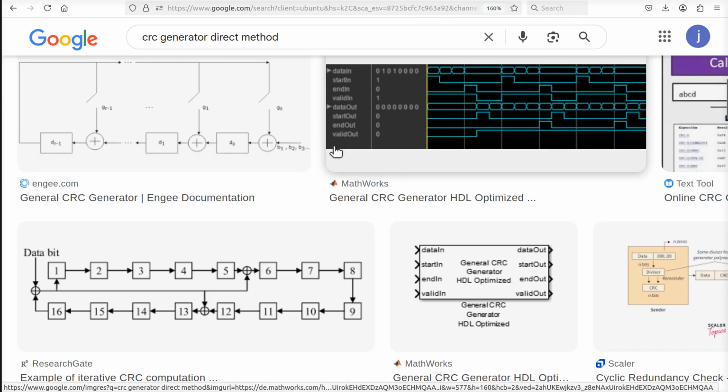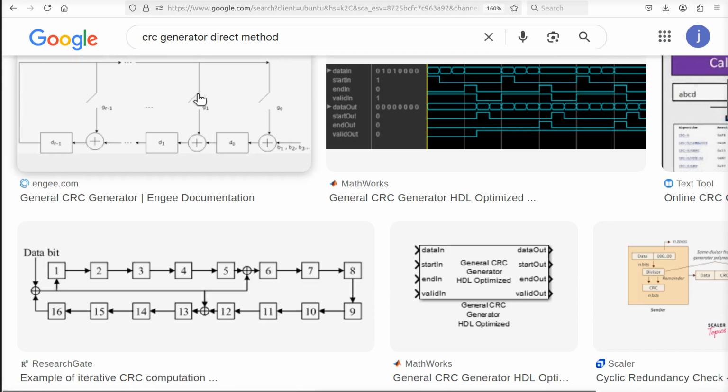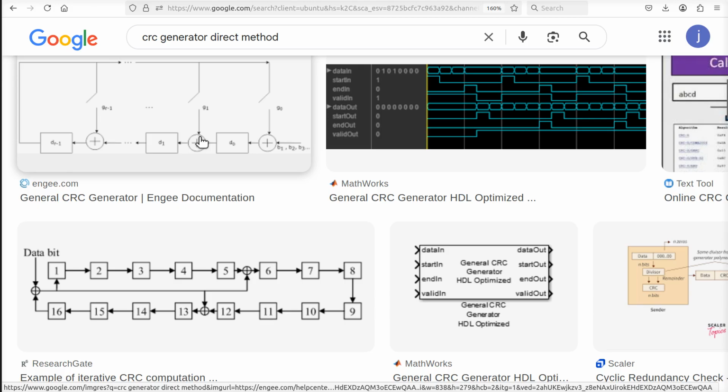So think about what that means. The data comes in from the lesser bit, and you're shifting left on each clock, okay? And the XOR gate simply will invert the data as it flows through here when the most significant bit is 1, because that's what an XOR gate does. If one of the inputs is 1, the output will be the opposite value of the other input. It's sort of like a gated inverter. If it's a 2-input XOR, that's what they do. If you don't believe me, go look up the truth table on Wikipedia or something like that. Convince yourself that that's true.